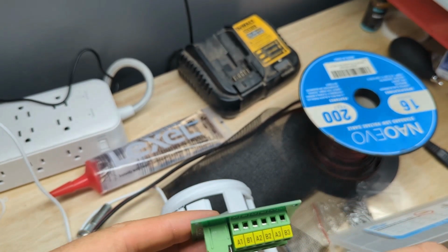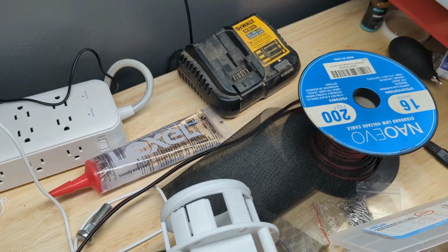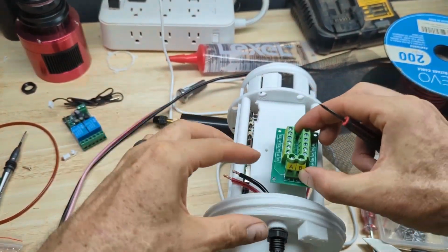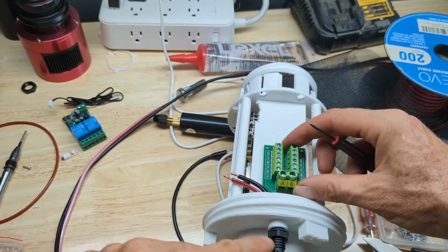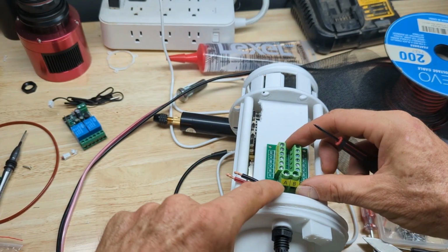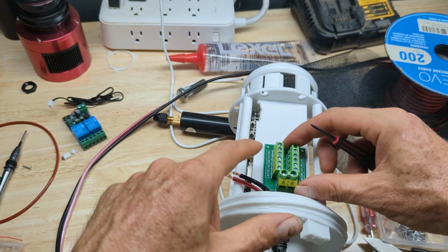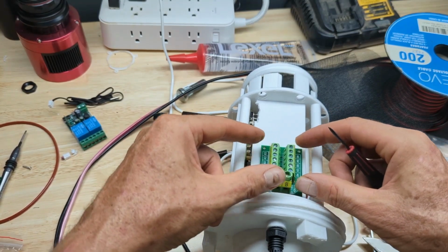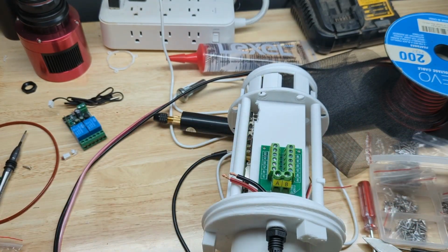So turn clockwise to actually tighten it and clamp the cables in, and then turn counterclockwise if you need to release the wires. So, all right, this is basically going to install right here at the bottom, and so your power comes up through the bottom, goes immediately into this port, and then from there you fan out your power to any device that needs it. So we'll go ahead and get this installed, and we'll be back to that in just a second.